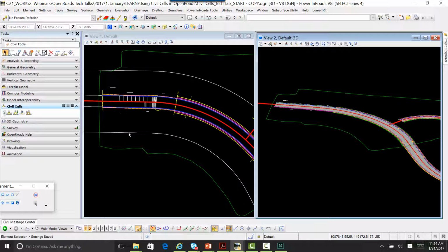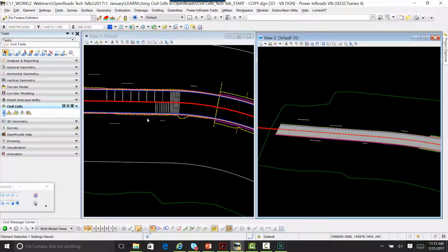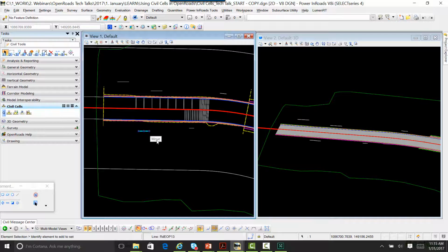All right, so we know we have a driveway, and we know that there's design intent that's been stored that we can access and reuse over and over again. So within my project here, remember, we've got this roadway that we're modeling, and the survey crew's gone out and captured these back of the driveway lines, okay? So those could have been generated from topo, for example. And now I've got multiple driveways along the corridor left and right, and I want to model that driveway.